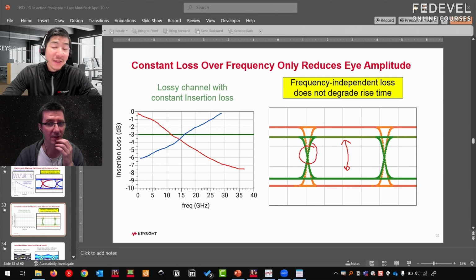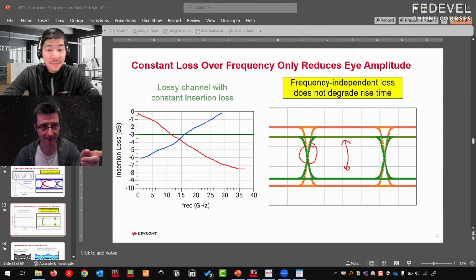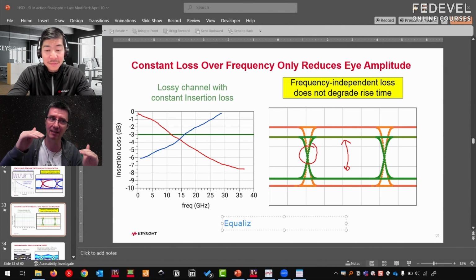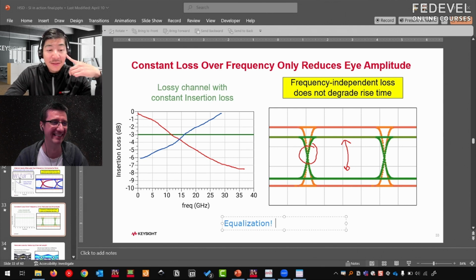We should explain this. How is it called again? Equalization. Yes. So basically, for very fast signals, the signal is corrected when it is received, and this is exactly one of the corrections we would like to do. For different frequencies, we would like to amplify the signal. So basically, we get a constant loss for the signal. Correct? Yep, exactly. Very good.